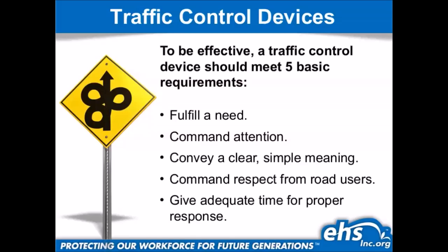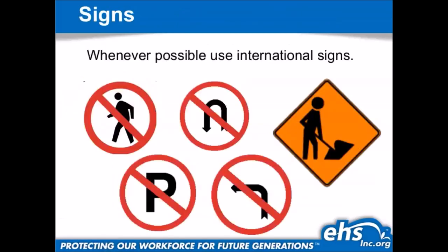The MUTCD says you should have those signs spaced out 100 feet from one another and 100 feet from whenever you're starting to affect traffic. That's 25 miles per hour or less. So you can imagine, the greater the speed, the more space and time you have to give them to read, understand, and react. And obviously, guys, that is more of a joke sign. It's not effective, right? It's not easy to understand.